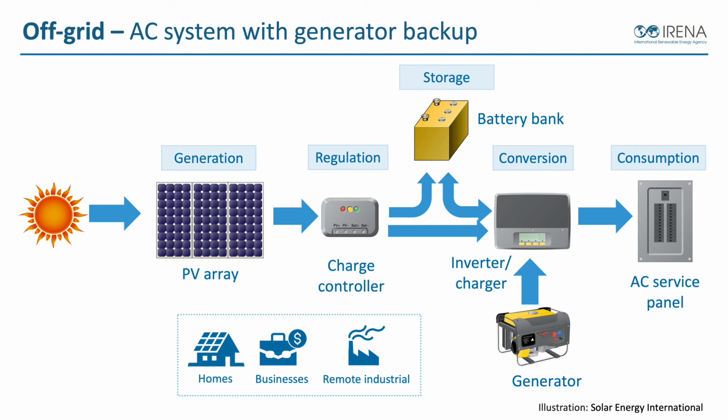And no matter how many cloudy days we have, as long as we have the generator as a backup system, we'll always have power. Now, with a more advanced inverter charger, depending on the quality and the complexity of the particular inverter charger, we can also do things with the generators like automatic generator start and generator control systems, if the inverter and the generator are capable of having those sorts of functions. And many of them are.